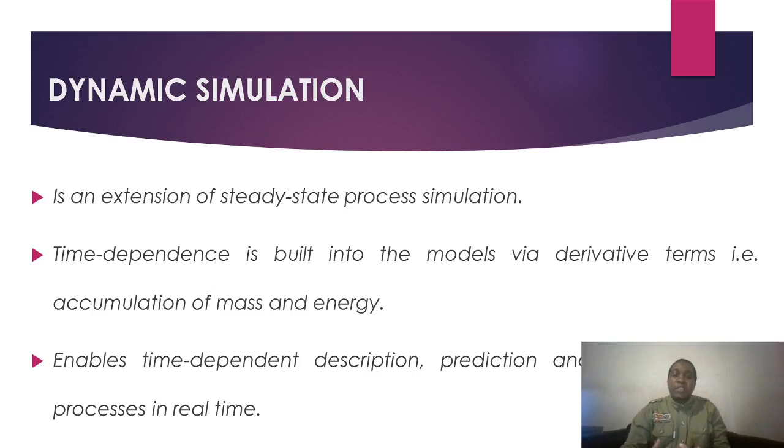So it is different from steady-state simulation in the sense that the mass and energy balances vary with time. In steady-state simulation, there is no variance in variables and no variance in mass and energy balances. But in a dynamic simulation, there are variations. There is time dependence of mass and energy balances, right?